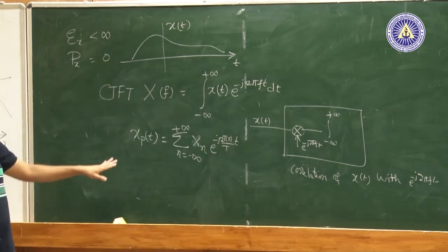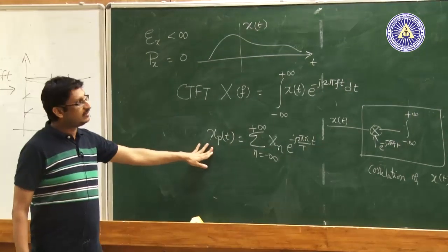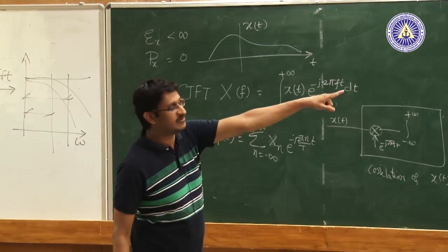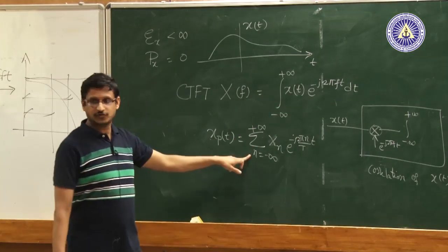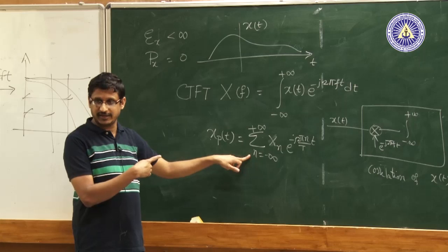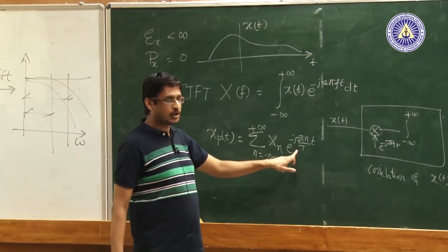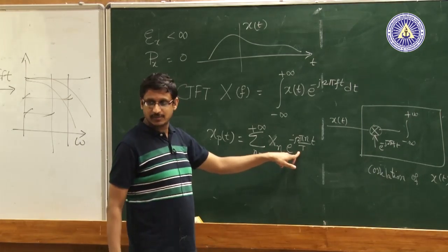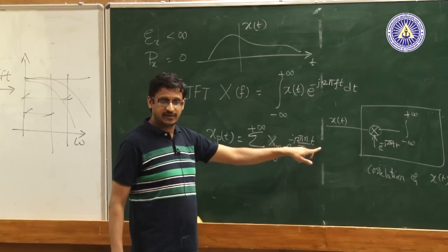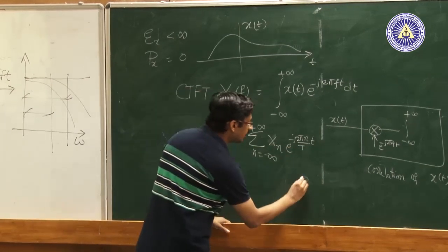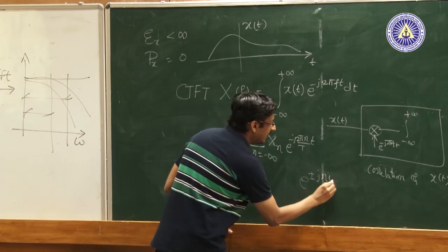I can write a periodic signal in addition to that Cn form that we have written there. I can write it in this form, which is called the complex form, wherein we are going to use the complex exponentials e power minus j 2 pi by T times n t, which essentially correspond to e power plus or minus j n omega 0 t.